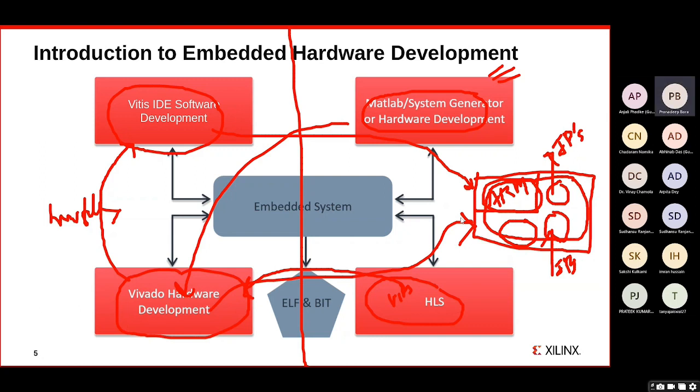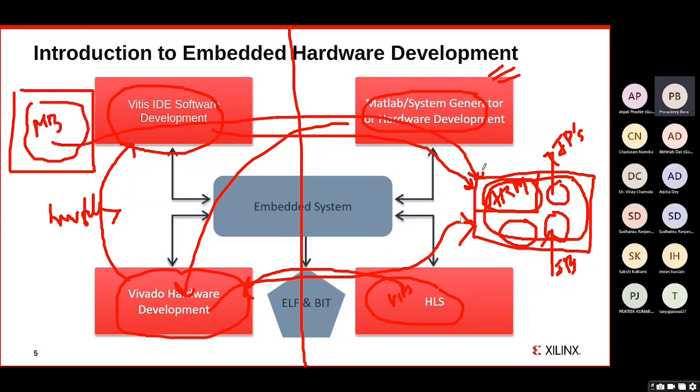And let's say if I want to develop a processing core inside an FPGA, there also one option is there. We have soft core processors, that is called the MicroBlaze processor. But it will not be as efficient as ARM because it will be spread out into LUTs, block RAMs, DSP cores. It will not be as efficient as this ARM processor. So the ARM processor will give that efficiency, along with the FPGA fabric giving me parallel processing power. So we can have a much better embedded system if we go with Zynq SoC designs.